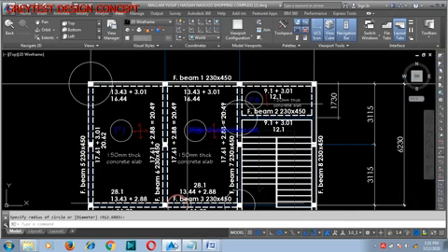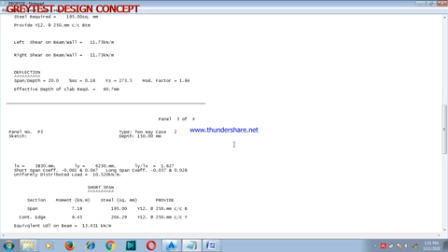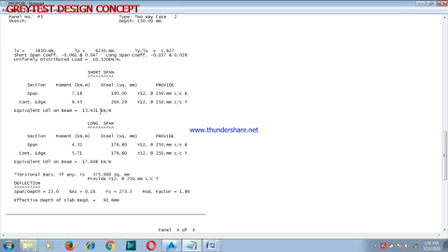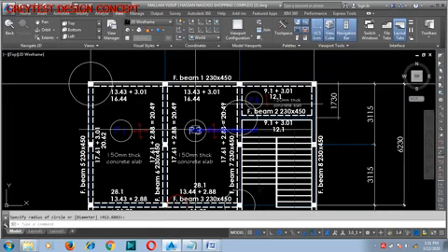When you go to panel 3, the same thing, 13.43 on the short span. What do we have on the long span? 17.608. On panel 3, short span 13.43, long span 17.61. Same thing with our panel 1. So that means panel 1 and panel 3 are actually identical.